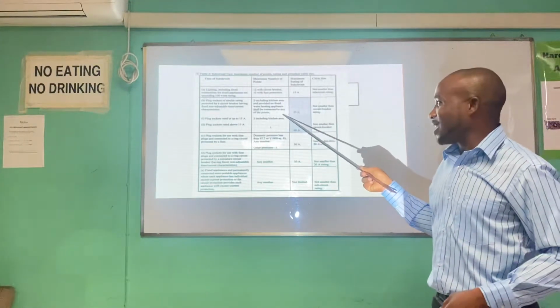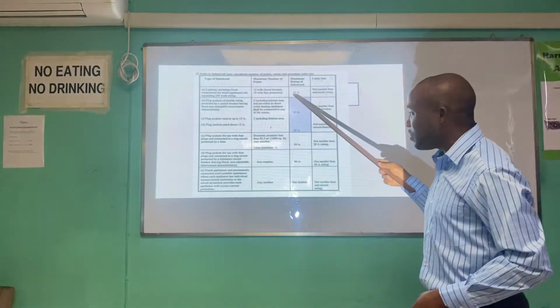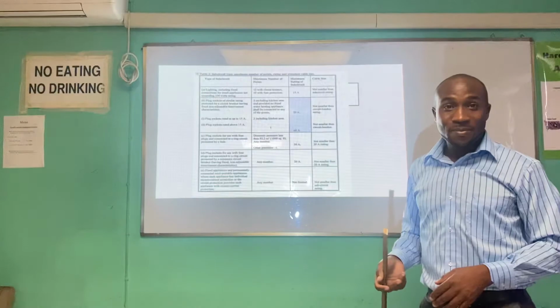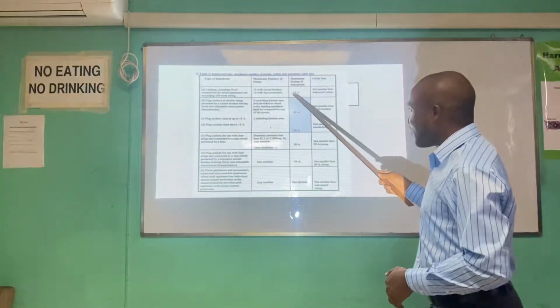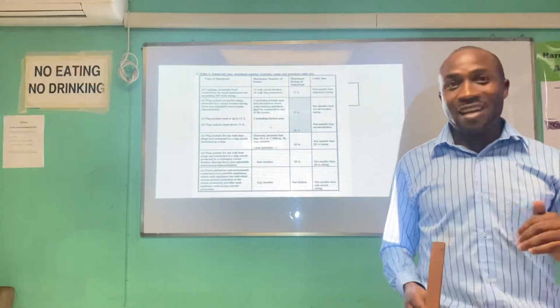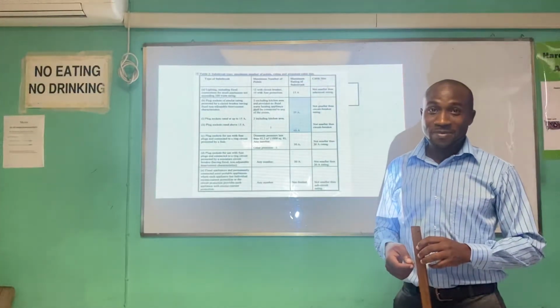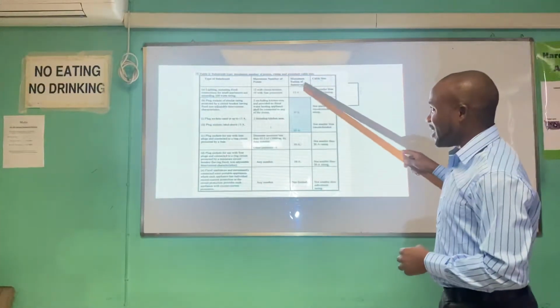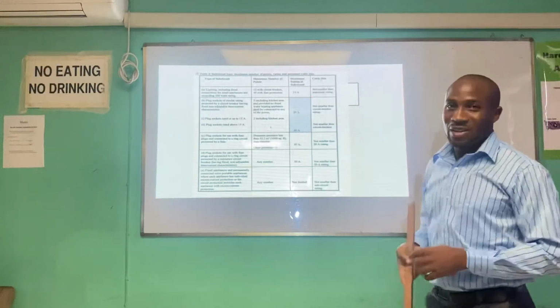And if you see a lot of 15 amp, you realize that those would be light circuits. 20 amp plug, 15 amp light. 20 amp plug, 15 amp light. Right, so that's the standard. That's what the regulation states. So it shouldn't be the other way around. You shouldn't have 15 amp for plug and 20 amp for light. No.